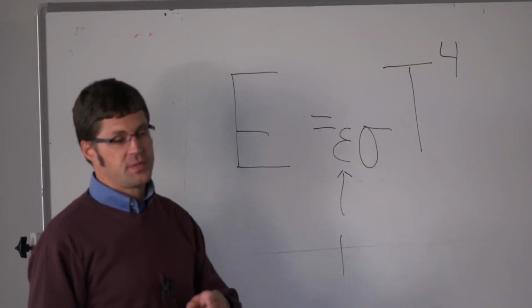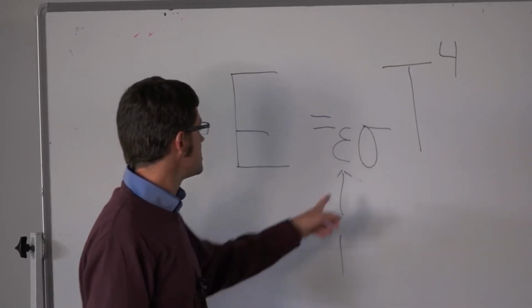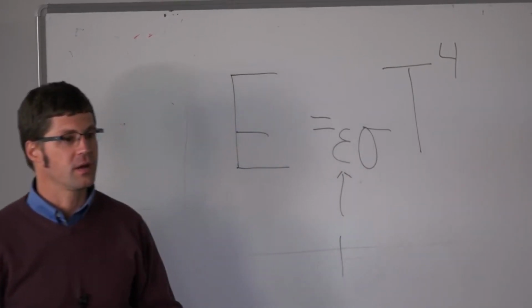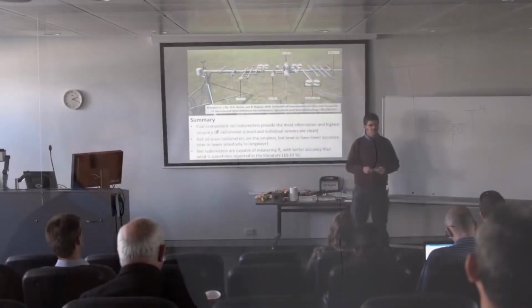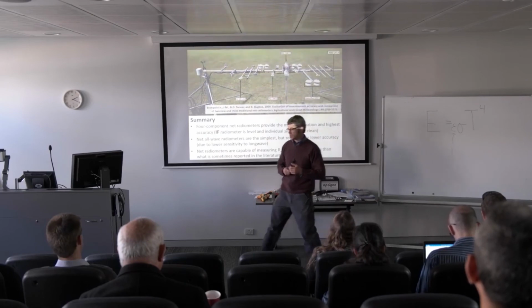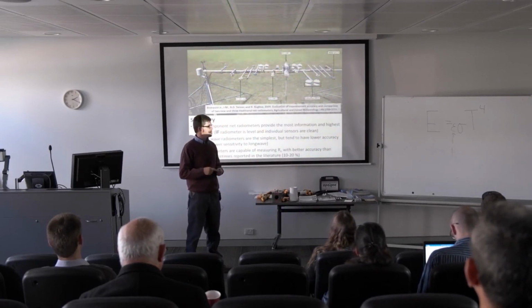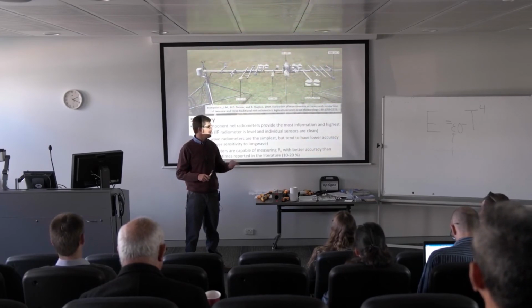The challenge with doing incoming longwave radiation estimates is this number is the hard one, and you were asking about that earlier. So there's ways to estimate the emissivity for the atmosphere, and that's where the humidity measurement comes in. It's usually empirical equations that estimate atmospheric emissivity based on sometimes air temperature, but typically the vapor pressure of the atmosphere.